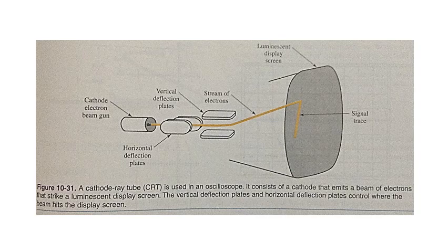Now a 60 Hz AC voltage is applied to the vertical input terminals. This wave starts at 0, rises to maximum positive, and returns to 0. It then increases to maximum negative and returns to 0. All of this occurs during one cycle. The period of this cycle is 1/60th of a second. Therefore, the horizontal sweep and the input signal voltage are synchronized. One wave appears on the screen.